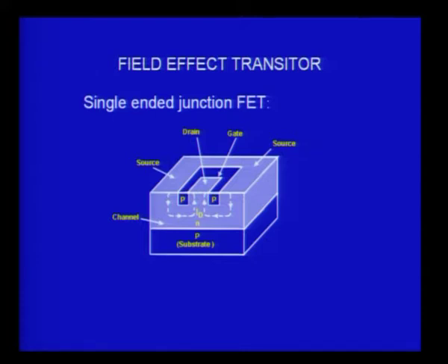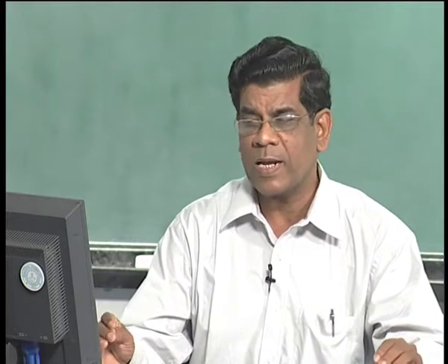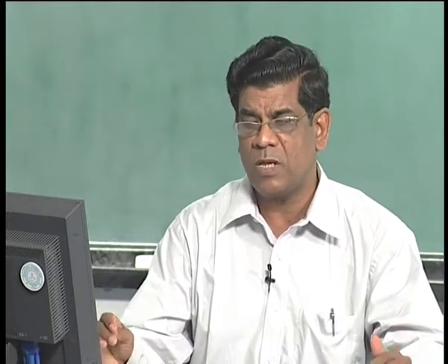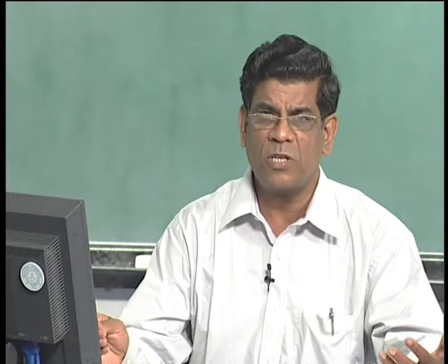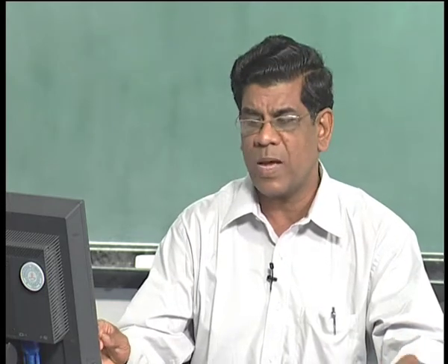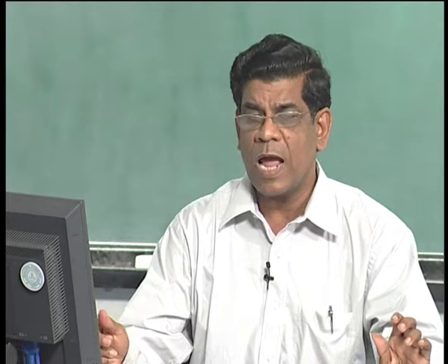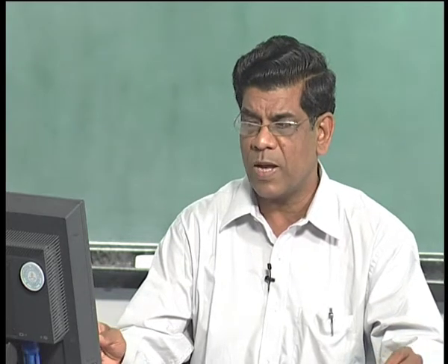Like that I can develop a number of integrated circuits, especially the field effect transistors, in very small regions on the wafer. If I also do the interconnections and the resistances using N type or P type semiconductor, then in principle on the same side of the silicon wafer I can generate all the components, the resistor, the capacitor. Capacitors are very rare, but you can generate capacitors because it is again the diode, the reverse bias diode, which is the usual capacitor that we have.